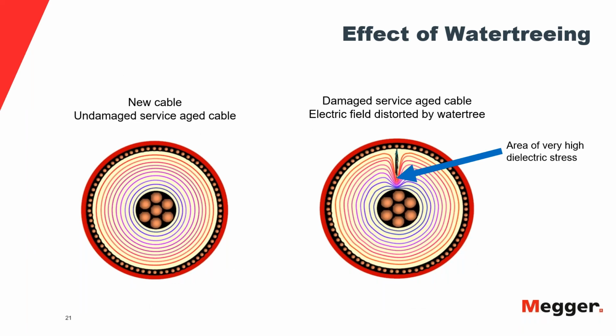Now, why is this water treeing effect such a thing? Well, before the tree retardant stuff was put into the ground, first and second generation PE cables suffered a lot from this. And also EPR cables have treeing as well, approximately as much as water tree resistant cables. And so a water tree is pretty much this pocket of water. There are various different models to explain this, with nano voids that are filled with water and then expand and all of these things. And the water tree grows over time and it distorts the field.